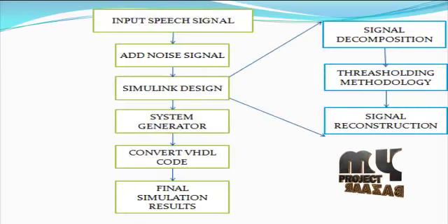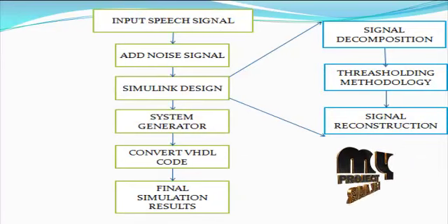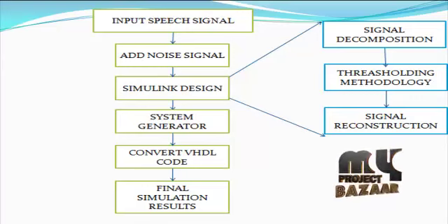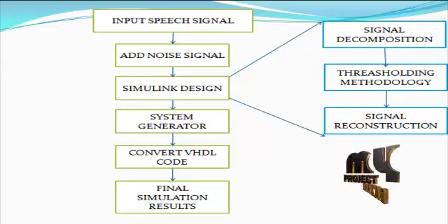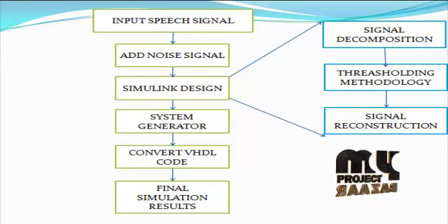Next we see the flow diagram for the product. The input speech signal is applied to our speech denoising methodology. We apply the MATLAB functions to the speech signal, then add the noise signal using MATLAB, with additive white Gaussian noise added to the input speech signal. Then we apply the simulation designs to this noisy signal. Our simulation designs are mainly based on Xilinx blocks, designed for the speech denoising methodology. These designs consist of signal decomposition, thresholding, then signal reconstruction.